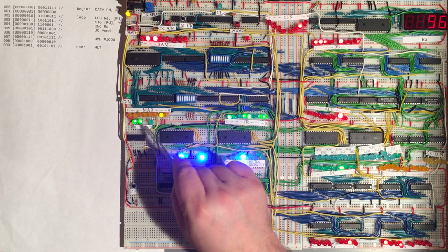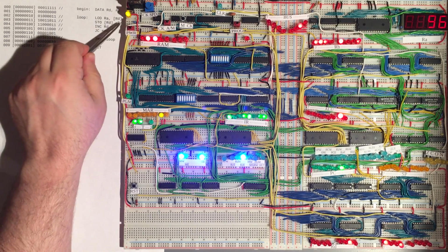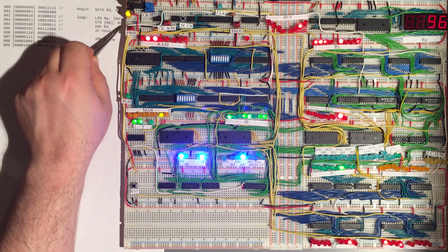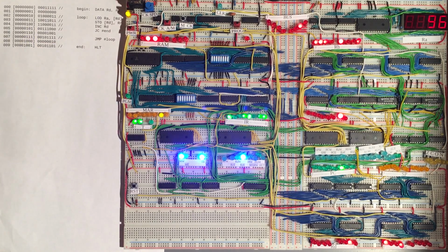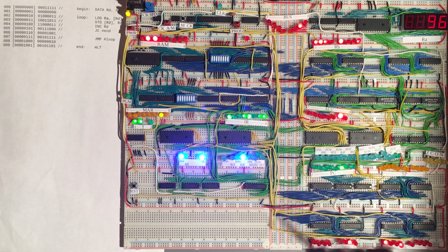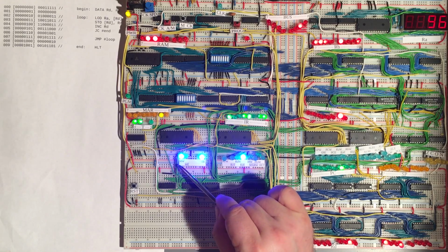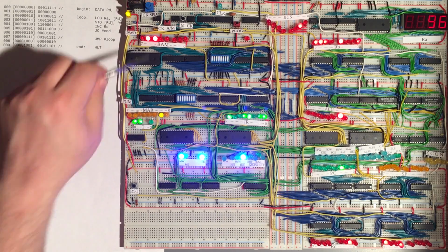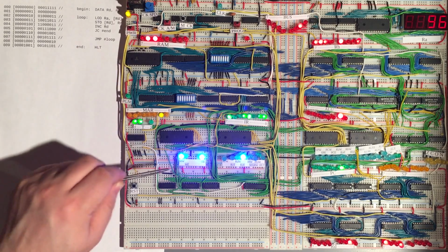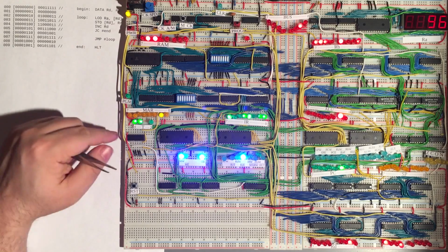And then on micro time t3, what we need to do is we need to get the contents of whatever register we want to write into RAM. Now in this case, those were both the D register, but they could be any combination of registers. So that register is enabled, the one which we want to write into RAM, onto the bus, and then subsequently we have a memory write signal, so that the RAM, which is now pointing to the correct address because we set the memory address register, will take the value which is on the bus and write it at that address in RAM.